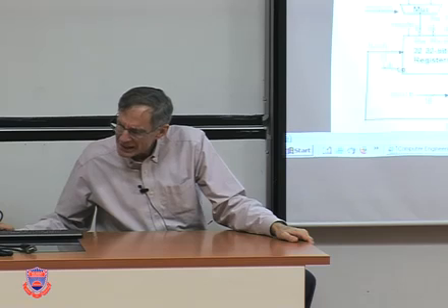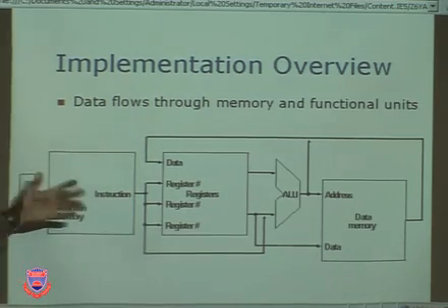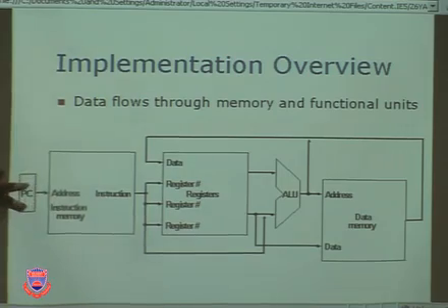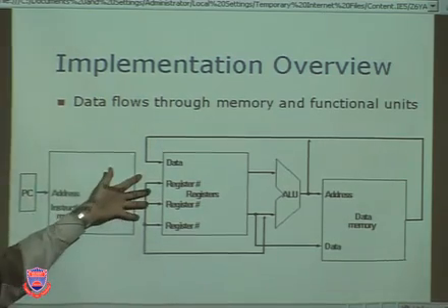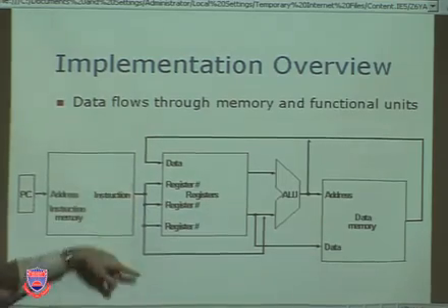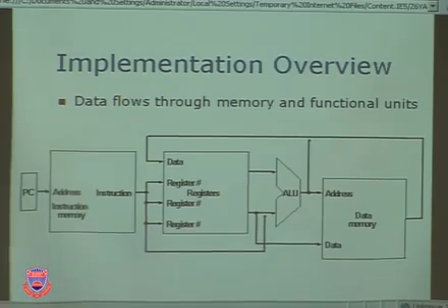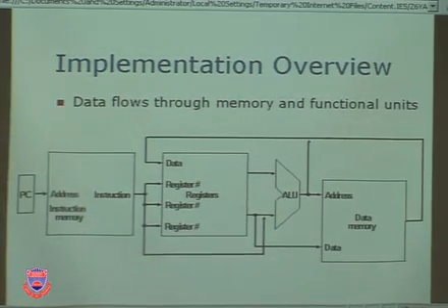What's the instruction fetch unit? Okay. Well, that's the last thing we did. So let's begin by saying, what did we think the instruction fetch unit was? In the beginning, way back, we said all we need to do is have a PC that gives its current value to an instruction memory, and this is the instruction address, and out pops the instruction stored at that address. This is memory. So you give the address, and out comes the thing stored, and it's the instruction. It's a 32-bit field, and so some of it is these registers, some of it's immediate. Remember, some of it is the actual opcode itself.